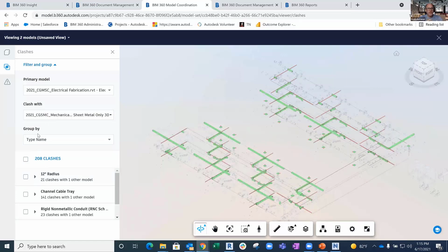That's only a fraction of what Navisworks does, right? So I didn't show the slide about saying this doesn't replace Navis, but I'm telling you now, this doesn't replace Navis. It just extends functionality. So I can't come in here and say, hey, I want to find all conduit 4 inches above and clash that with these girders or whatever, right? So you don't have that granular ability, but this is enabling me to come in here at a high level and run some clashes if I wanted to.